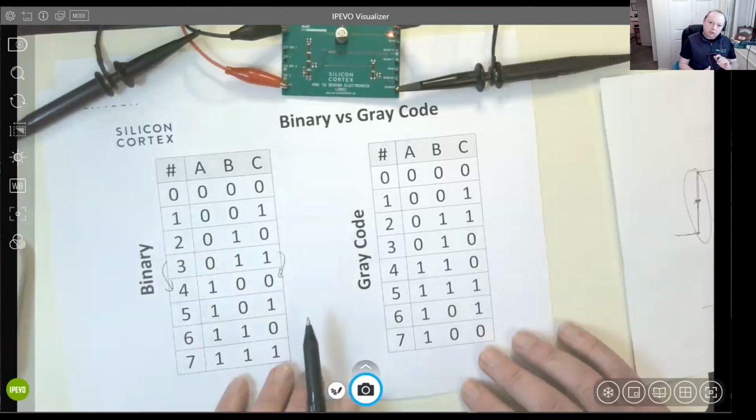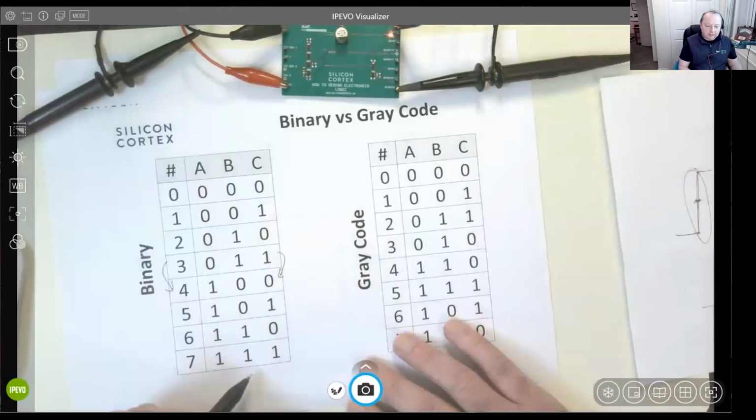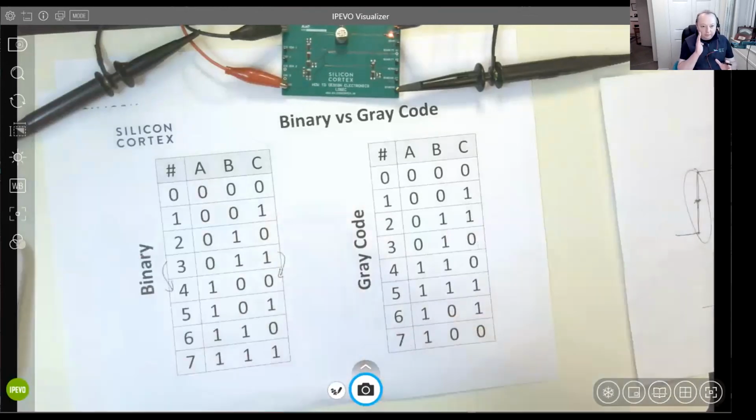And so the way which often you'll fix that is, whilst your logic's going fast, you then have to synchronize it with a clock, and that would have to be a time later to allow the voltage levels of the gates to settle. It's called settle time. So the clue's in the title, really.